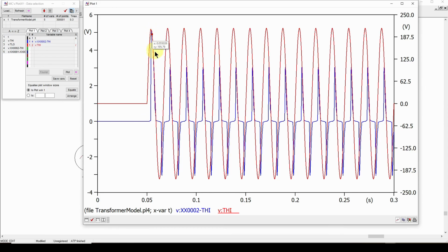Then as the source voltage comes down, that shuts down because the flux has dropped. Now you're in negative territory, the flux is increasing, and finally you get to the point where it shoots up again at negative. You can see why this current goes up: it's hitting saturation at each of these points.